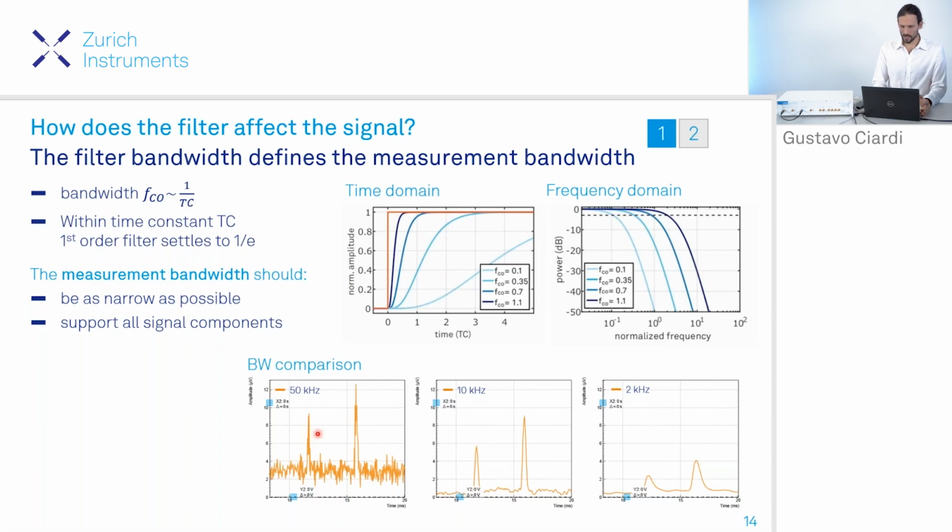Here I have a signal with 3 different low-pass filter settings, and we can start with the left-hand side. We can see that the signal is visible, however, there is quite a thick noise background that you clearly see overlaying the signal. This is with a quite high filter bandwidth.